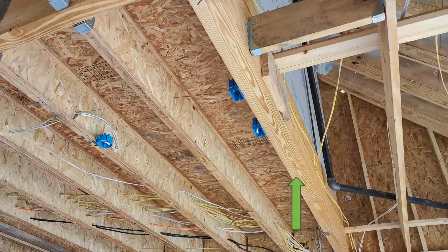But Energy Star also looks at that as a pathway for contaminants. That's why they also mean that needs to be blocked. This is a conditioned subfloor over a garage. We talked about this on a previous slide. Underneath that beam should have a gasket, a poly seal, something that's going to stop air movement into that subfloor. And then all penetrations running horizontally through that floor must also be sealed if they go through that exterior band joist part of it. And then all the electrical boxes should also be air sealed.